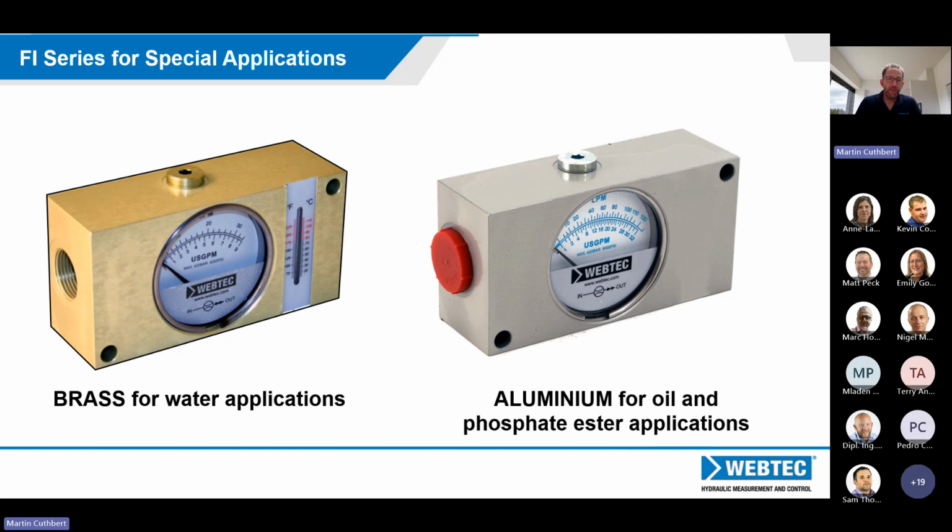And the unit on the right is calibrated for phosphate ester. Two main differences there. One, this one has been calibrated for a lower viscosity, sort of 11, 12 centistokes. Secondly, phosphate ester, for anybody who's hopefully not in contact with it, but is familiar with it, is a very aggressive fluid, should never get it onto your hands.